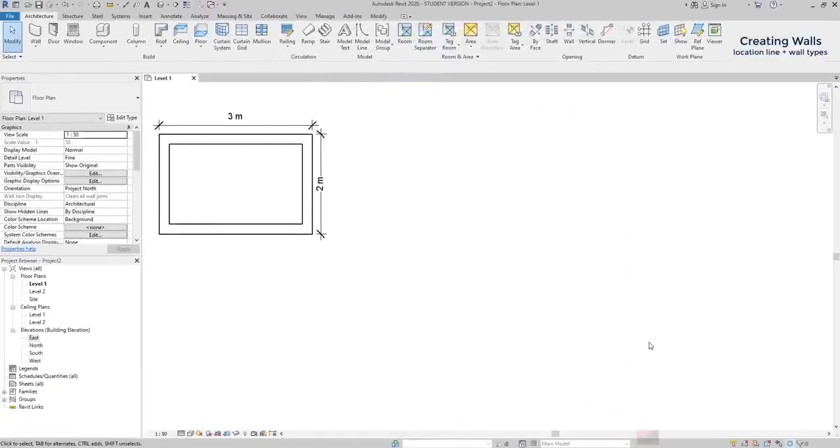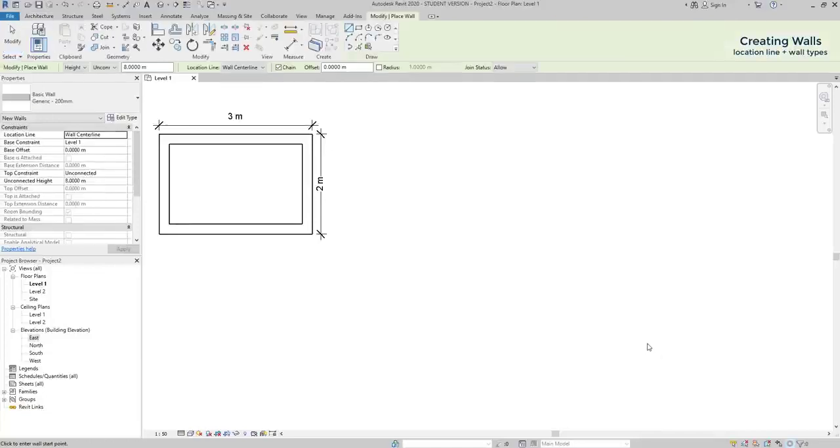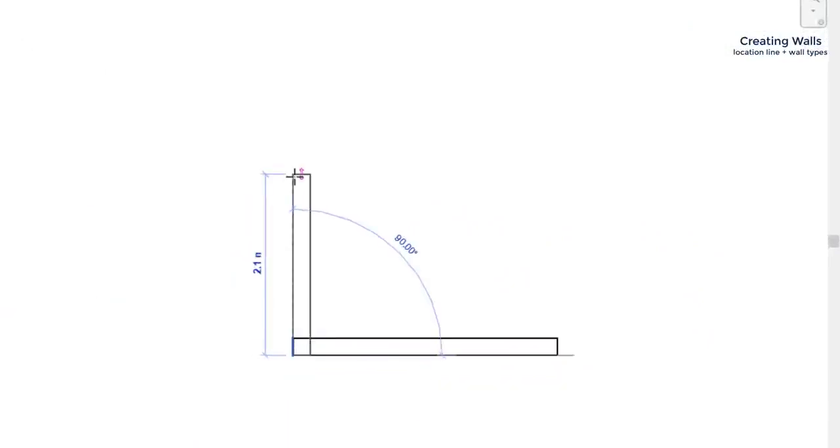Now, let's look at the next example. Here, I have these walls with external dimensions. If I click on the Location Line tab, I can see these different options. I will explain them after, but for now, I switch to Core Face Exterior. Basically, the location line is located on the external side when I draw clockwise.